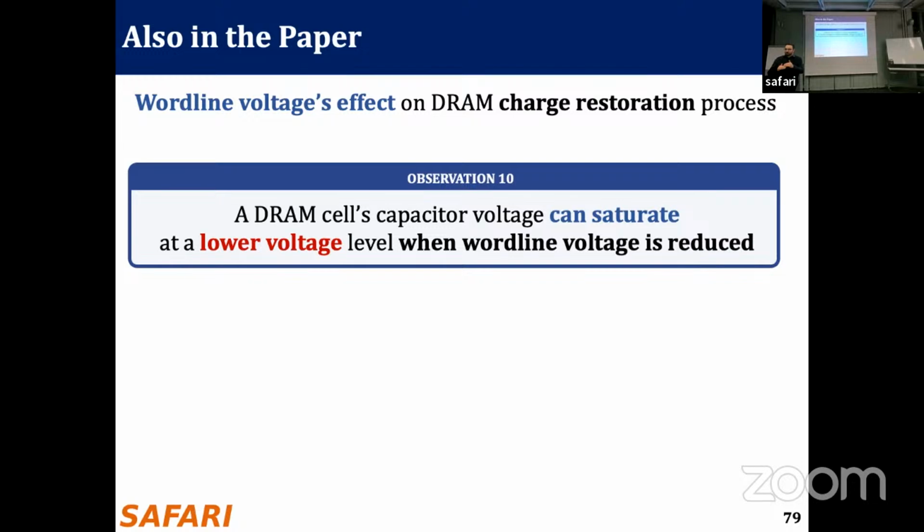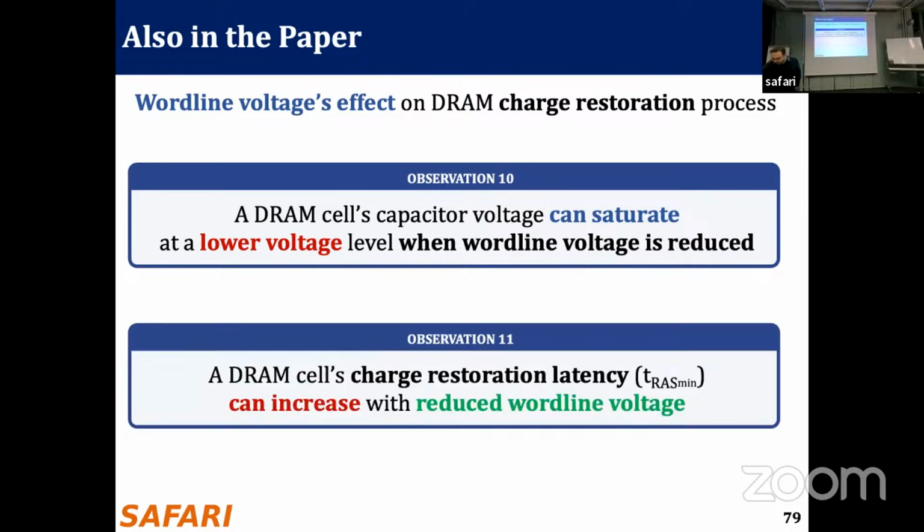So if you consider it goes to full VDD, for example, it cannot go, right? Because as you reduce the gate voltage, the channel disappears after the source voltage reaches some lower amount, and then it saturates over there.